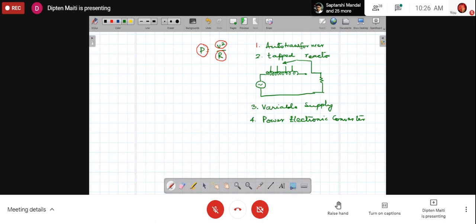However, even if the output of the chopper is controlled by using a closed loop structure, that should not be considered closed loop control of the heating, because the temperature, which is the final control variable, is not sensed and is not used as feedback. So this would not be considered a closed loop system if you are using the voltage of the chopper.